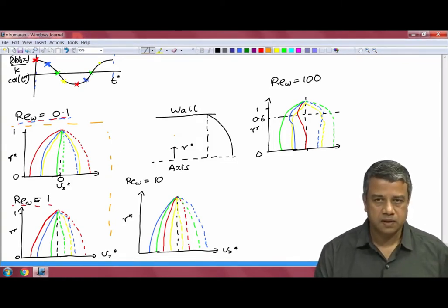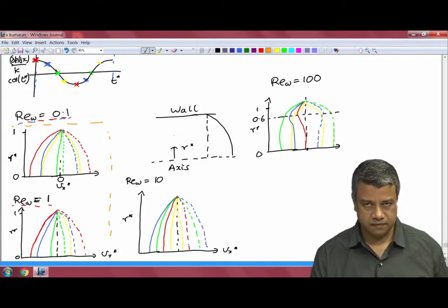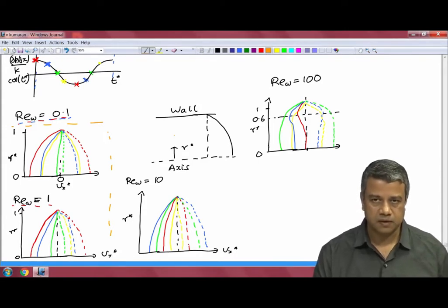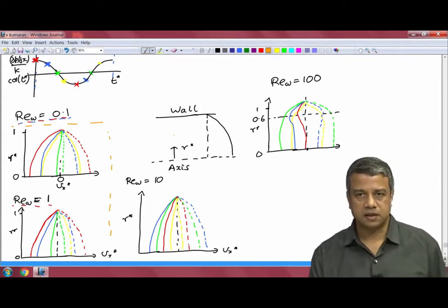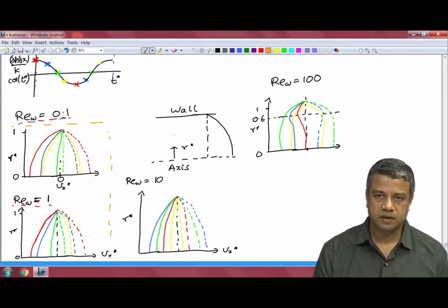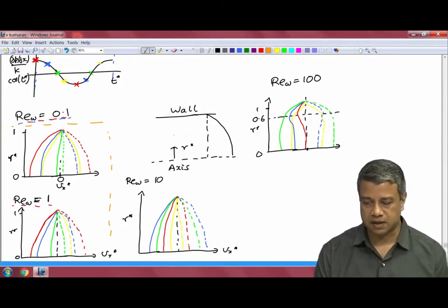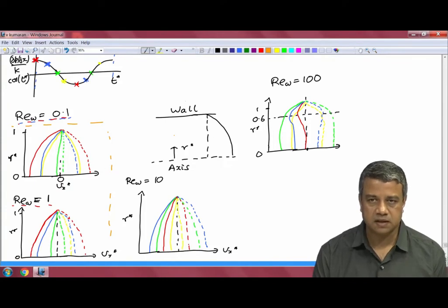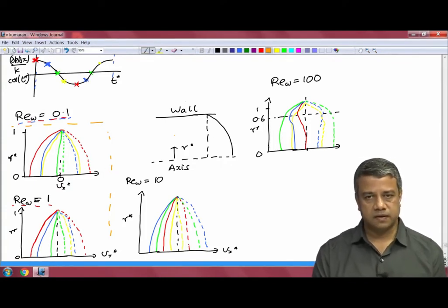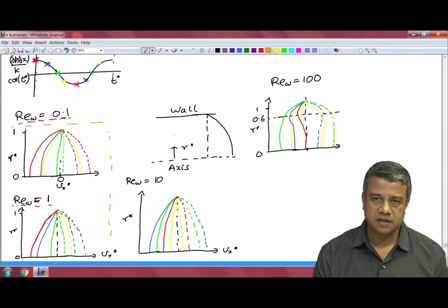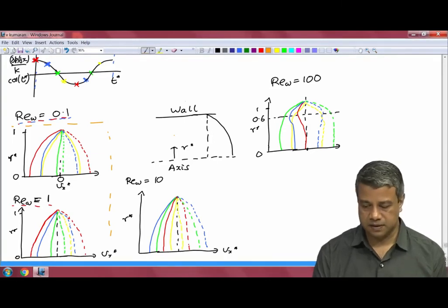At low Reynolds number, the profile is nearly parabolic. When the pressure gradient is a maximum positive, the velocity has a negative minimum parabolic profile, and it is 0 when the pressure gradient is 0, and has a positive maximum when the pressure gradient is at its minimum, negative value. It is similar to the velocity profile you would have got had you taken the instantaneous value of the pressure gradient for a steady profile, in the limit of low Reynolds number.